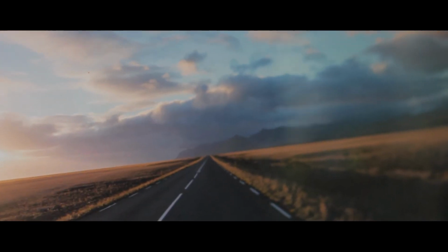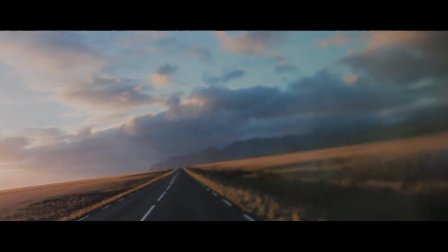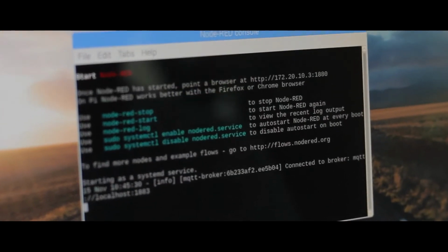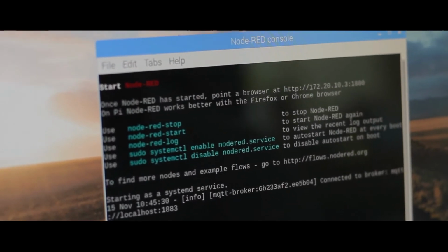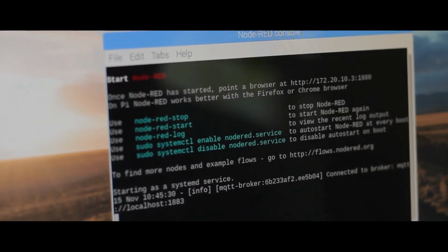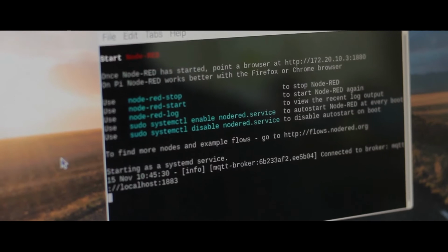For the next part, sensor data will be uploaded from the Node MCU, an open source IoT platform, to the MQTT server. This is done by using an MQTT broker on a software known as Node-RED, which is installed in the Raspberry Pi. The MQTT broker, in our case known as the Mosquitto, is installed on the same Raspberry Pi the Node-RED is running in.